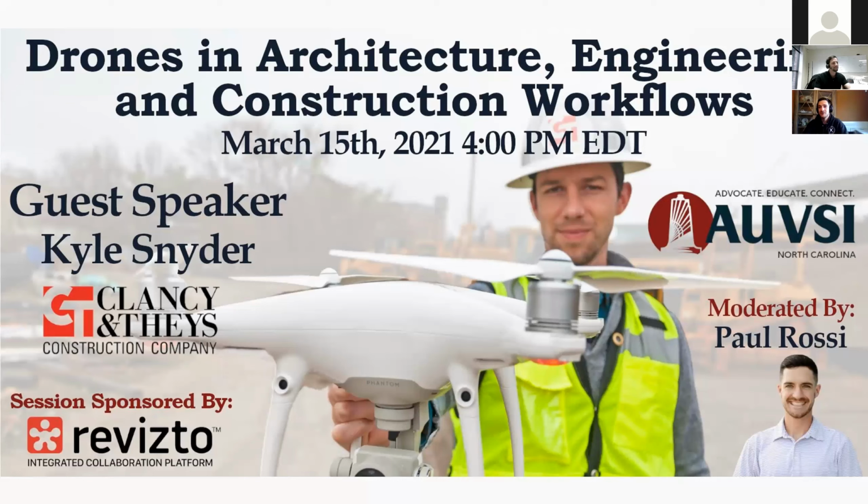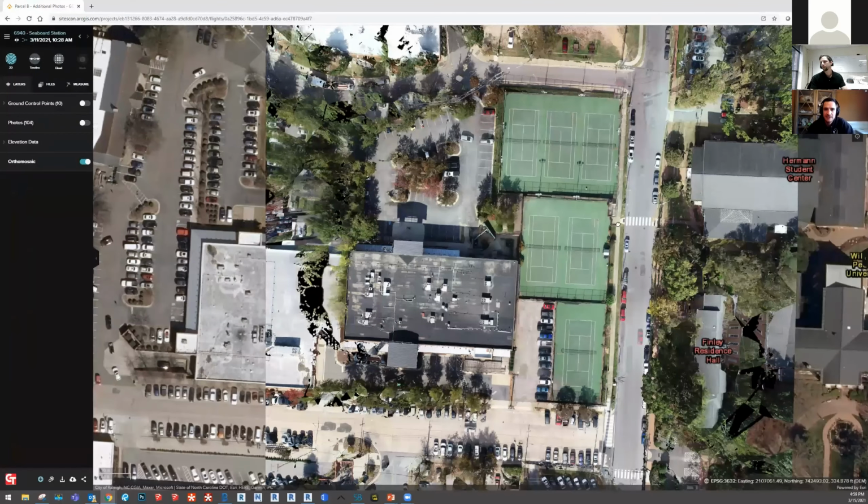GCP, so I guess just for any of the folks here at the end of this, as things wrap up and we disperse, ground control points. So ground control points, it's using known points within a site that you're mapping, taking the exact coordinates, and before you process these images into maps, models, you can actually incorporate that known location data. And what that will do is that'll increase your models. And here we go down the hole, right, Kyle? That's going to increase your geo accuracy in regards to where this is in regards to the actual Earth, and not just your internal accuracy, your relative accuracy as far as how long is this.